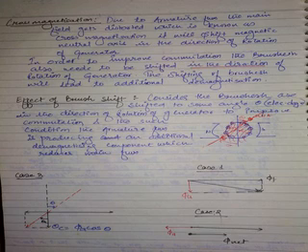Now, what happened? This is MNA, new MNA. So brushes are also shifted onto new MNA. So how is the armature flux now? Is this armature flux or not? This is the armature flux. What will this armature flux do to main flux? It will have two effects now. Previously, when the armature flux is just downwards, it is only doing cross magnetization. It is only shifting the phi F down. But now this phi A will do two things: cross magnetization as well as demagnetization. How? You will understand clearly.